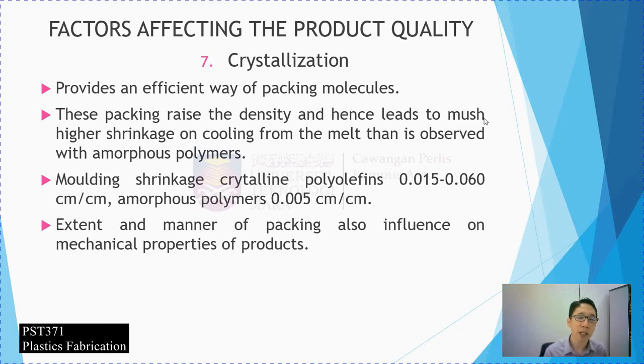Some of the materials and product shapes require extensions of the application of pressure using the packing, because the mechanical properties are strongly dependent on the pressure that you apply during the crystallization itself.